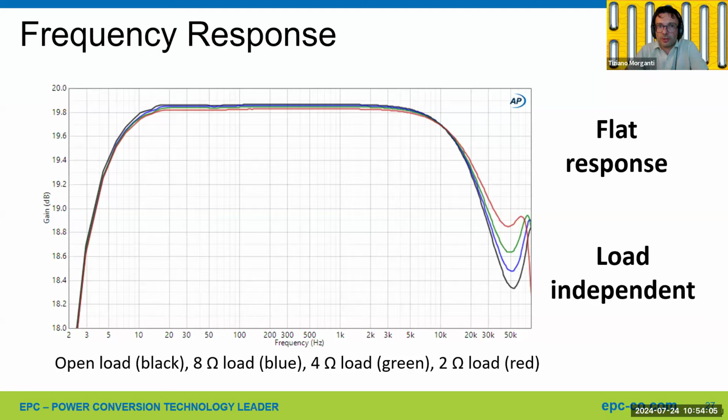So this kind of feedback is using this to close a first inner loop. Then we have another voltage loop that is using the output voltage and is operating mostly in the audio bandwidth. But we didn't try measuring directly the current from the inductor and using it to close the feedback. So I hope this is answering the question.